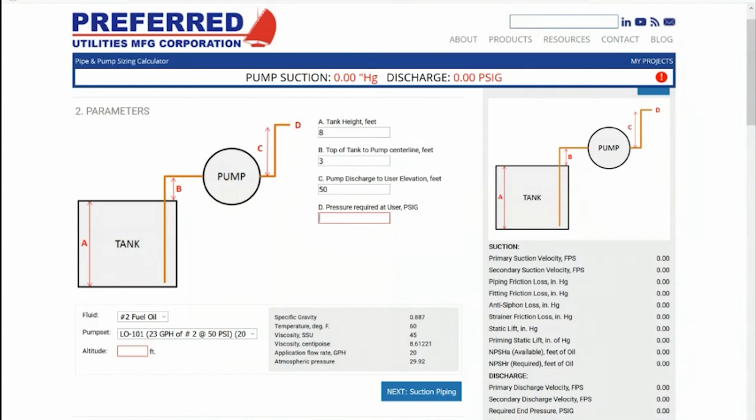We've got 2 types of pump sets, 50 psi discharge and 100 psi discharge, that are in our catalog, but we can also use rotary screw pumps that can go up to about 300 psi for the real high-rise applications. They're just kind of a custom pump for that application.